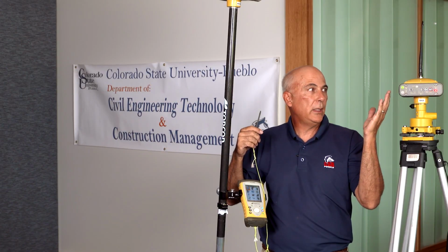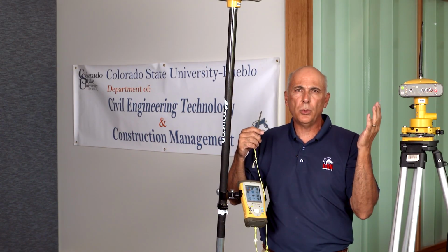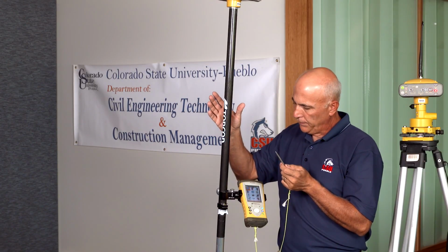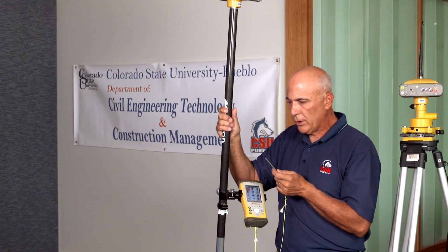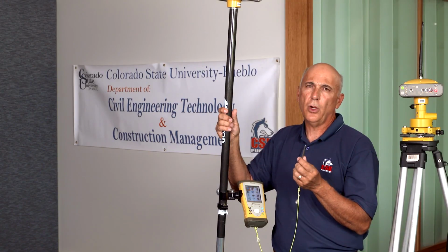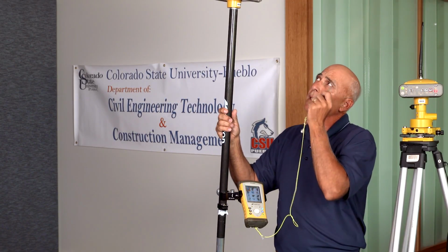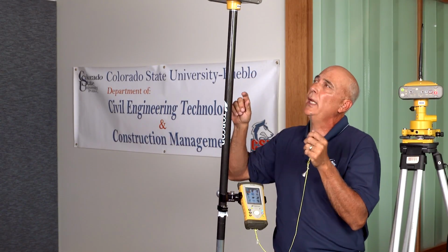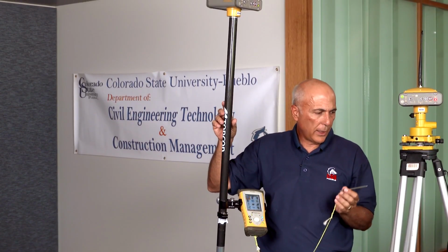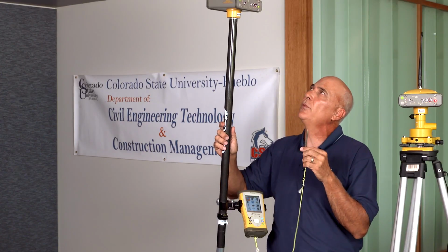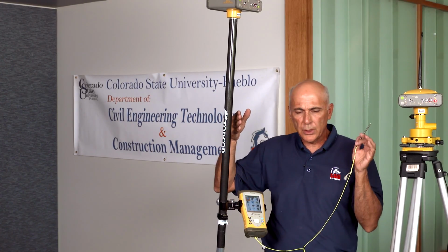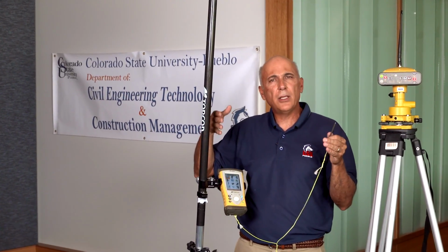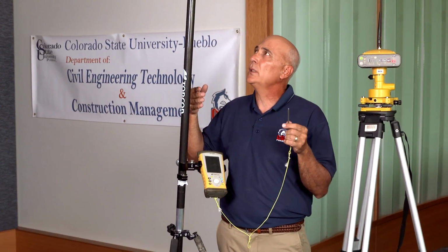The GPS technology works because the base unit knows where it's at. It's sending that signal to the roving unit. The roving unit, through a series of computations and using the same satellite technology, the same satellite coverage, can determine where it's at, and it will then apply a correction factor that's been given from the base unit, and the two units are now communicating. So we can get sub-centimeter accuracy between the two units.